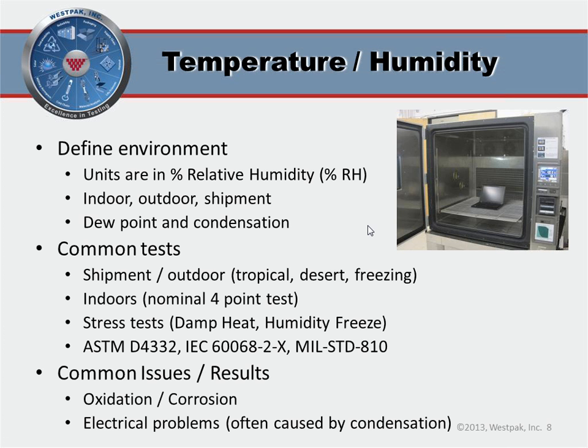You go to a high heat, either 65 to 85 degrees C, and usually a high relative humidity of 85%. Have the product in a chamber for up to 42 days or 1,000 hours and see if you have moisture issues, looking through seals or other things.